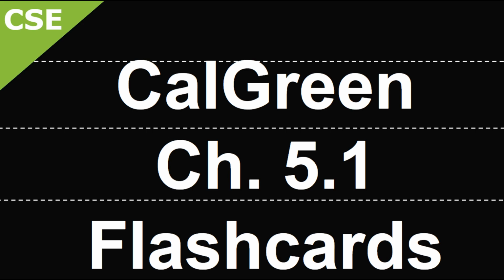Let's discuss requirements for electric vehicle charging stations, or EVCS. These are new updates as of July 2024. Based on the number of electric vehicle charging stations required, which means an EVCS is an EV-capable space with an EV supply equipment, or EVSE. That electrical vehicle charging station can be a level 2 or a DCFC. However, at least one level 2 EVSE shall be provided.